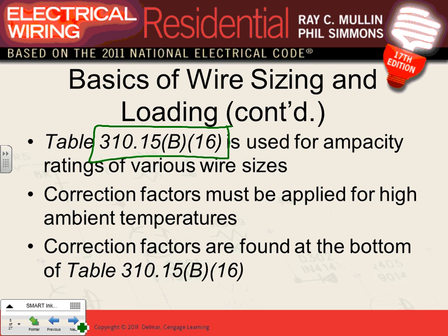So when we use the table, there's some derating based on temperature and derating based on current-carrying conductors. They're no longer at the bottom of the tables; they group them in a standalone table. And again, we will be looking at the derating table based on temperature. What does derating table mean? I have a conductor that can carry 50 amps, but I grouped it with another 5 conductors that are also hot. They will interact and heat each other up, so I have to derate it. Otherwise, it will be heating up more and it will fail.